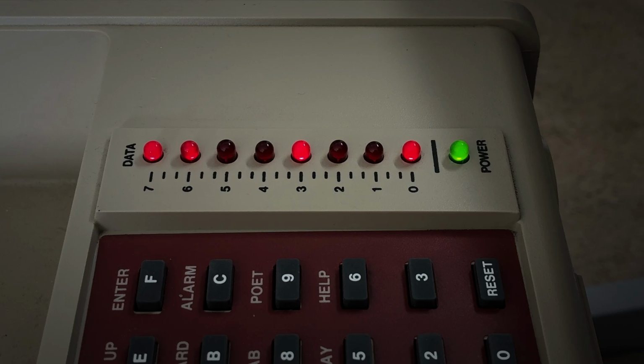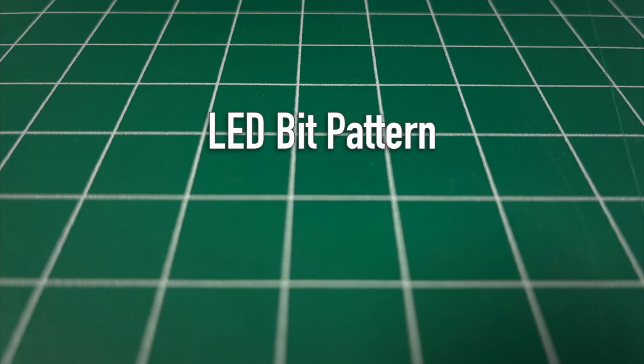The 8 LEDs on the Junior's keypad represent the 8 bits of a binary number. So let's imagine a pattern of 8 LEDs with 1s for lit LEDs and 0s for unlit ones. How about this pattern? That's the value that we need to load into the A accumulator before we call LED out. The only problem is, it's a binary value and we need a hexadecimal one.